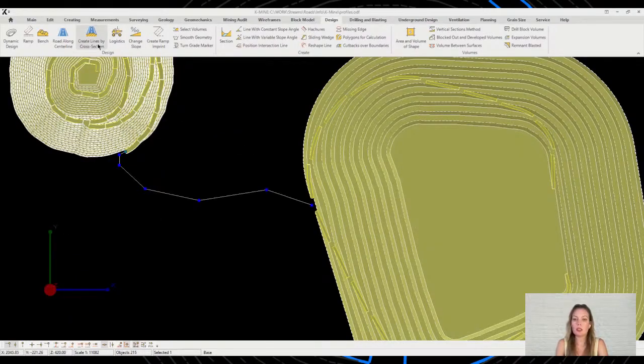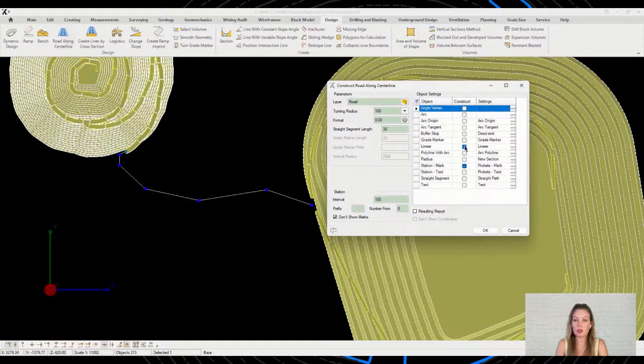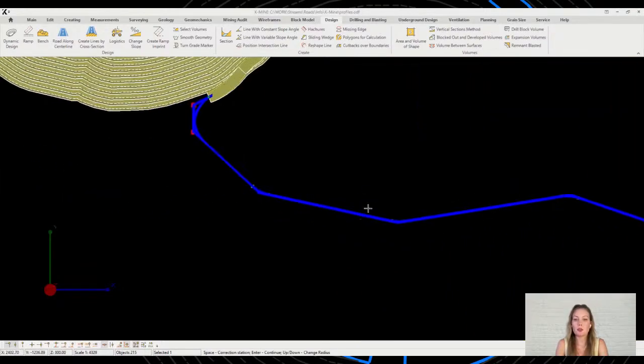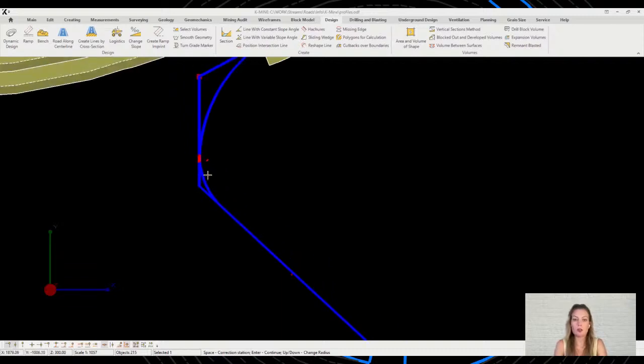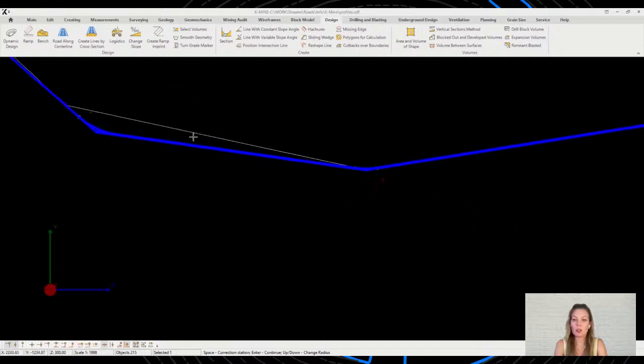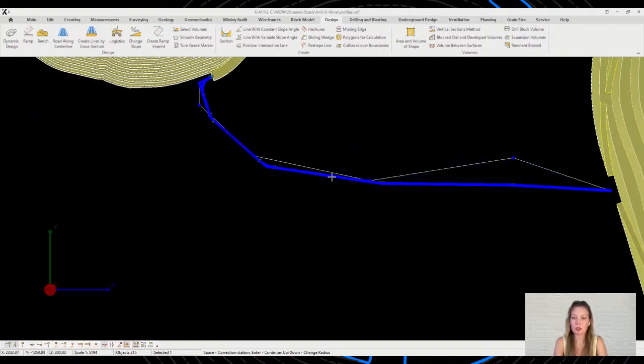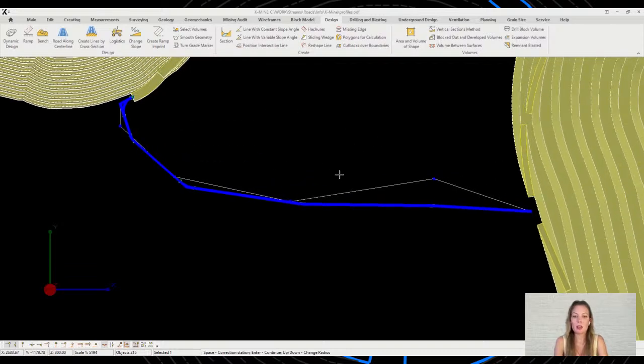To start the building, we need to draw a guideline, which will serve as a formation guide for us. Next, we need to turn this line into the center line of the road. To do this, we use the road along center line command. We configure the necessary parameters and proceed to dynamically changing the construction parameters. Places where the specified radii do not fit will be indicatively marked in red. To correct the situation, we can change the radius of the road curvature and move the position of the point.